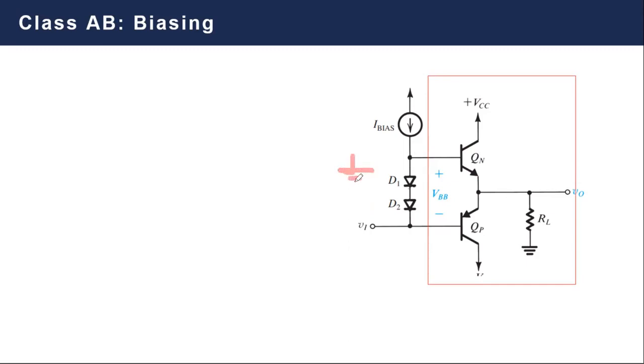So as if you have two voltage sources in series, each with the built-in potential, which is, let's say, 0.7 or something like that. So by putting these two diodes in forward bias, you make this base-to-base voltage equal to 2 times the V on of each diode.